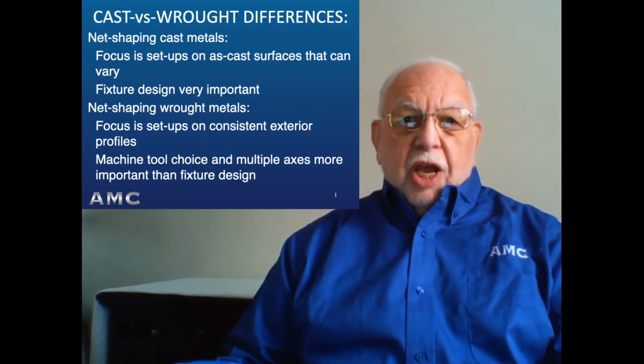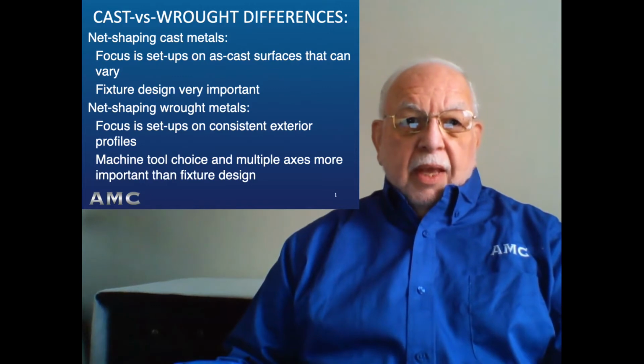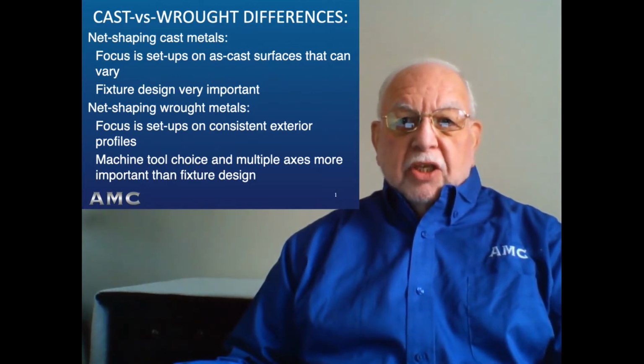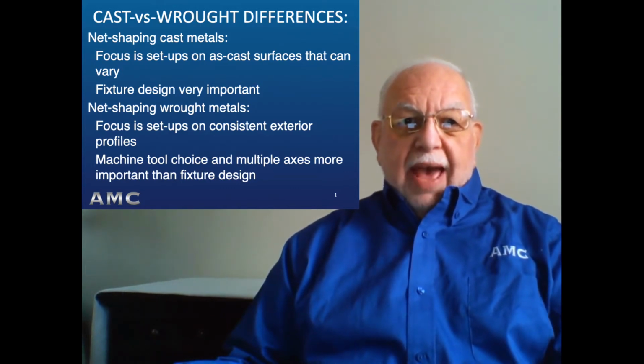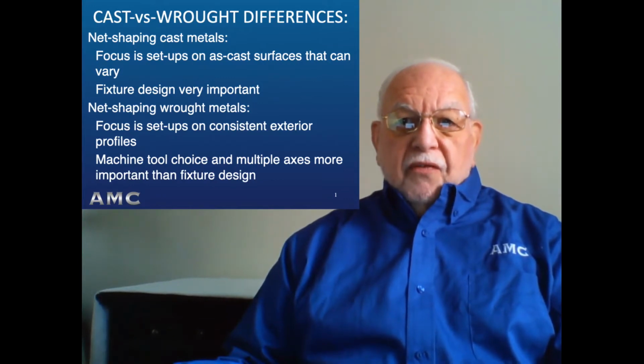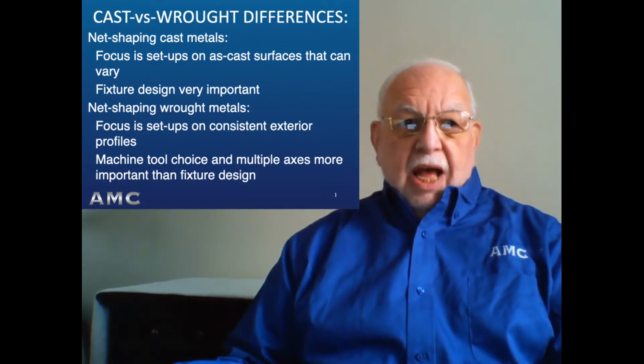Machine shops in general realize that wrought shapes are consistent in exterior profile, and the focus is on the type of machine tool, its basic orientation, its cutting pathways, and the number of axes needed to accomplish net shape. Fixture design is focused on orientation and axes, not consistent setup on surfaces that may vary.